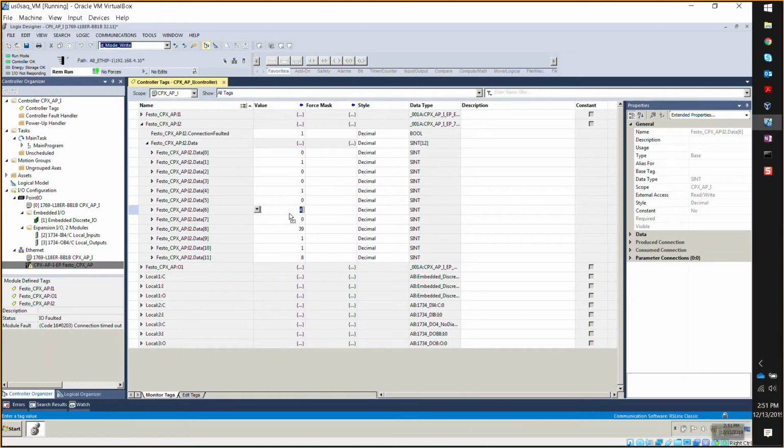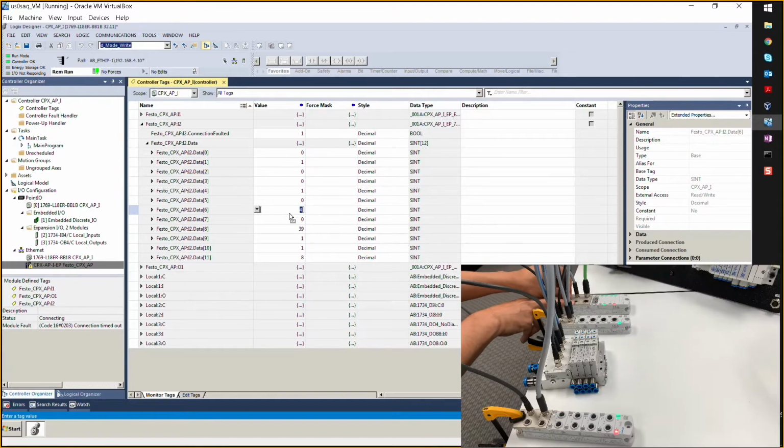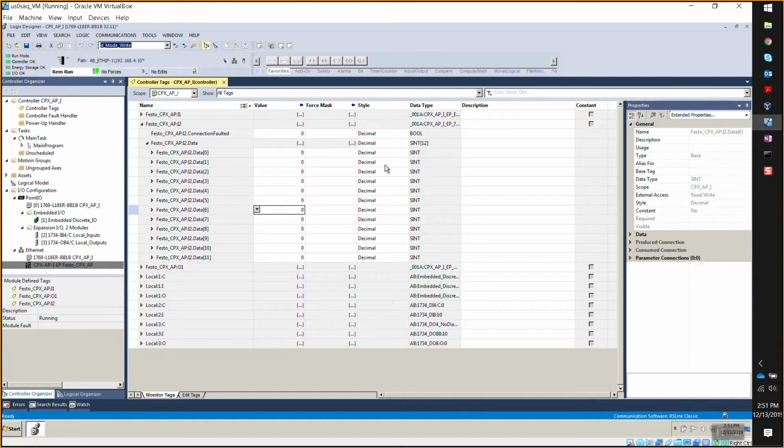So this is an example. These are examples of a basic setup for the API system with Ethernet IP. But we have one additional feature in here that I think is very important, and it has to do with doing parameterization, which may not come up in every case, but if you have more advanced modules, or even for this example without just simple outputs, if you wanted to hold last state, that's a parameter that you need to set. We have a nice new way of doing that here, and it's called using our L5X export function.